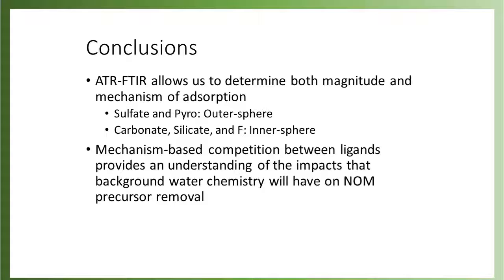So ATR-FTIR allows us to determine both the magnitude and mechanism of adsorption. We know that sulfate and pyrophosphate are outer sphere; carbonate, silicate, and fluoride are inner sphere. And this mechanism-based competition between ligands provides an understanding that the background water chemistry impacts this NOM removal, this DBP precursor removal.